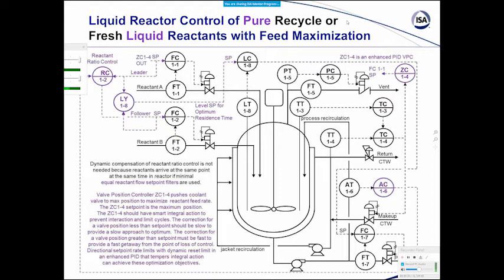We're trying to make sure that there's always some reactant available. So there's got to be a little bit of excess reactant, and that's what this composition controller is doing here. If any of the reactant concentrations go to zero, the reaction stops. And because you've got a continuous situation here, the other reactant is flowing out unreacted, so you don't want that to happen.